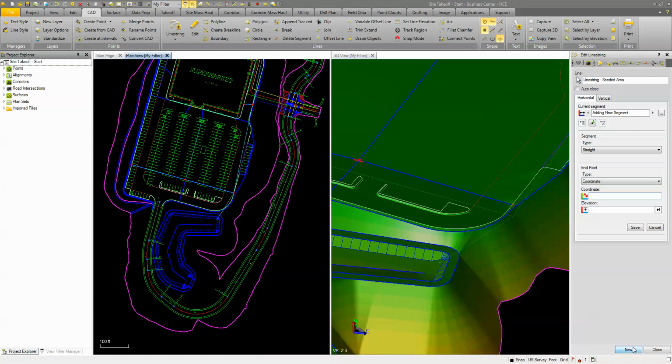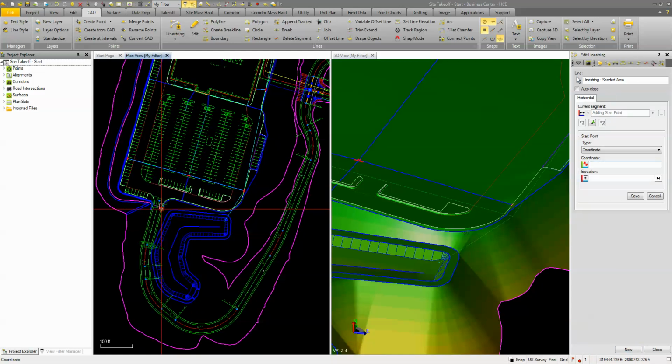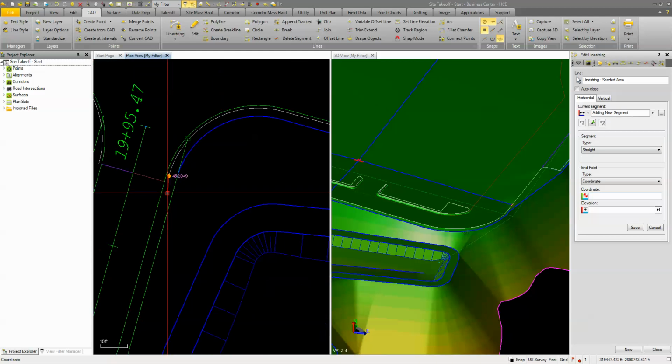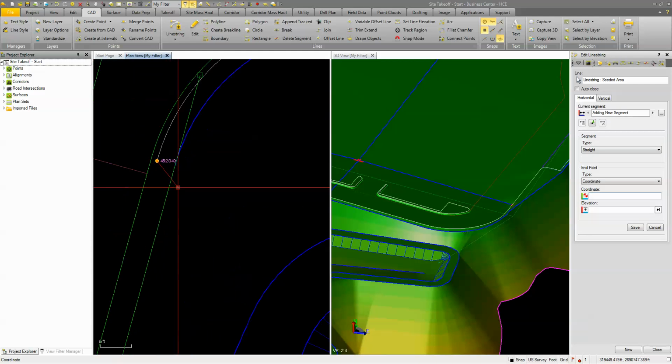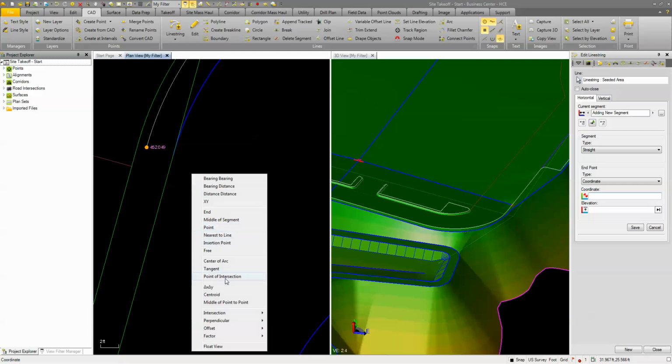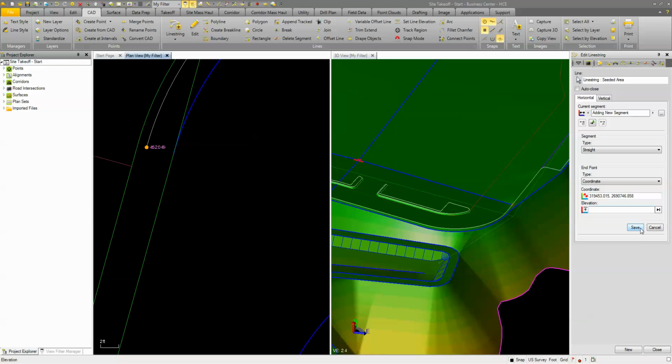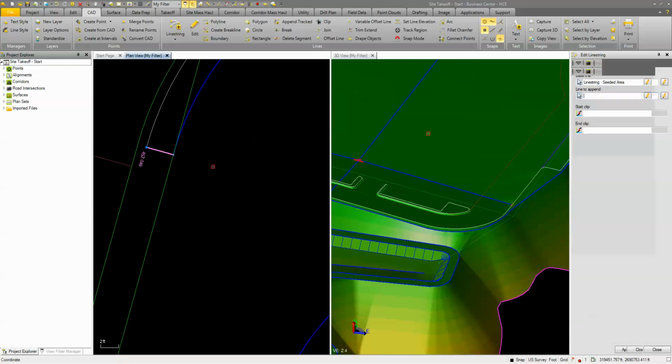We're going to do one more new one, where I'm going to come from the top back of curb here, and we're going to go to this, which is our shoulder. So I'm just going to right click and go perpendicular to here. So again, I'm just drawing in some boundaries here, and we're going to do the append line command again. Use this as a guide.